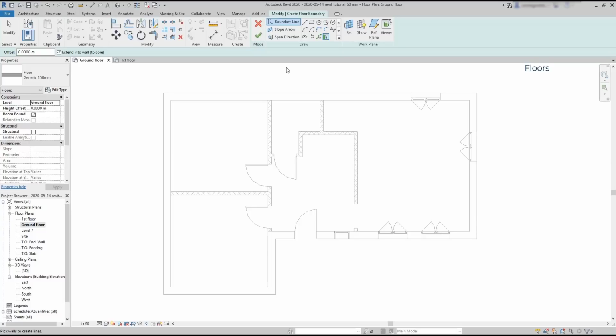But let's proceed. To draw a floor, it uses by default the boundary line, and to make it, I can use a line, rectangle, arc, among other geometries, or this last one, which is currently the selected one, called Pick Walls. I'm going to choose it, and you will see that it's actually very simple. I only need to click on the walls until I reach a close boundary.